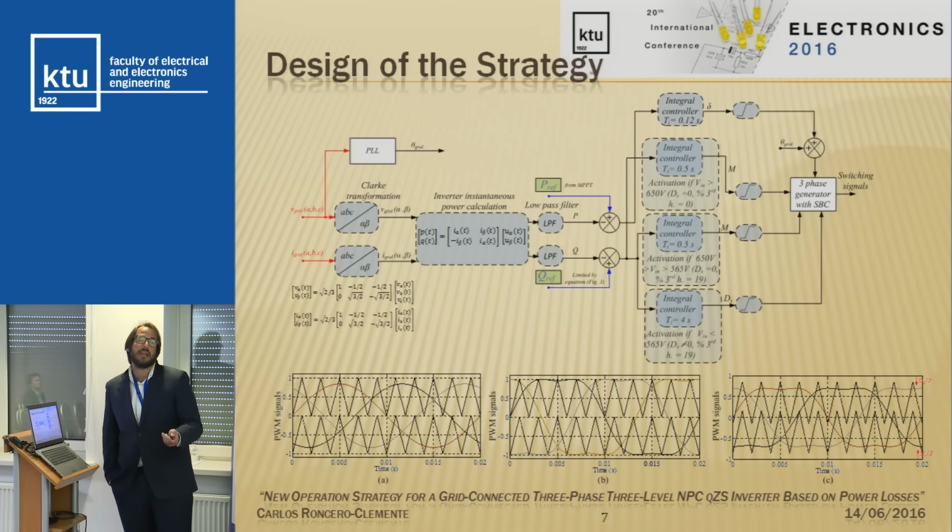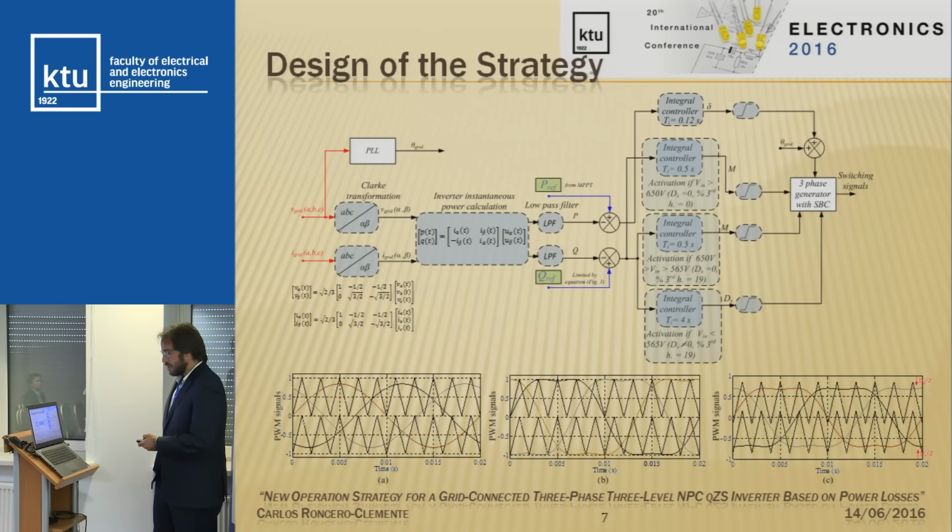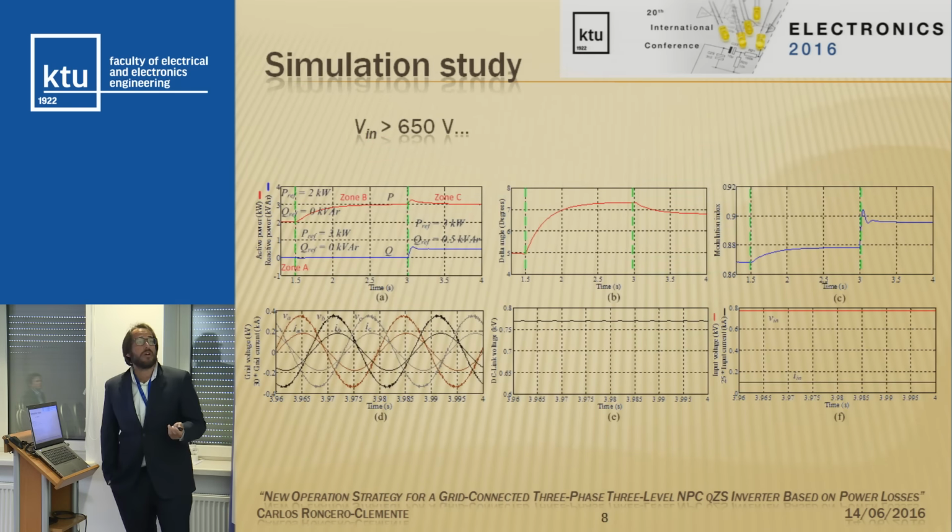Here we can see the main switching signals in each modulation technique: without third harmonic injection and without shoot-through; here without shoot-through and with third harmonic injection; and here with third harmonic injection and also shoot-through. Now we are going to present some simulation results that validate the previous operation strategy.